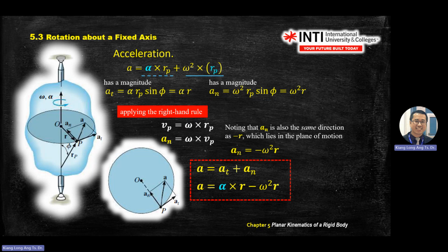So these two vectors actually go opposite to each other. So when you derive your equation from normal, in the r term you get negative. The vector just tells you that an is actually opposite to the r axis, the radius axis. Radius is always positive when you increase r, but an goes inside the circle. So in vector form, it should show negative. Anyway, this is the important equation. You just memorize it, look at the question, and substitute.